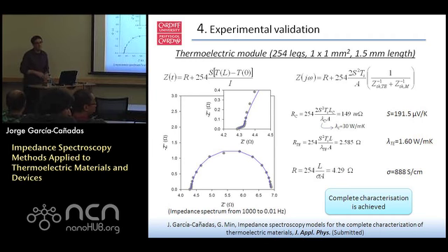So the devices that could be characterized are ohmic devices. I mean, you can't characterize a p-n junction, right? You can characterize any electrical device, really, because you apply voltage and you record currents. If you have a device, it should be linear, but your current amplitude is very small. You are always in a kind of linear regime, so you can characterize nearly any device. That's why it's very powerful, and it's been applied in a lot of ranges.